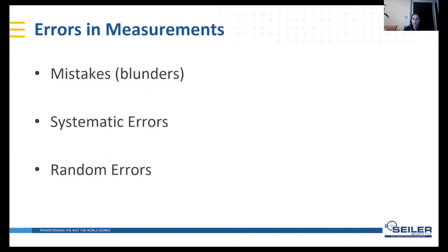So why do we apply network adjustment? We try to eliminate some of the errors that belong to our measurements, and we can categorize these errors as mistakes, blunders, that might be an incorrect height of instrument, an incorrect point ID, or a wrong shot, a wrong point measurement.